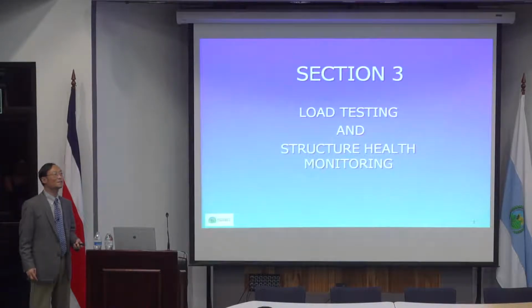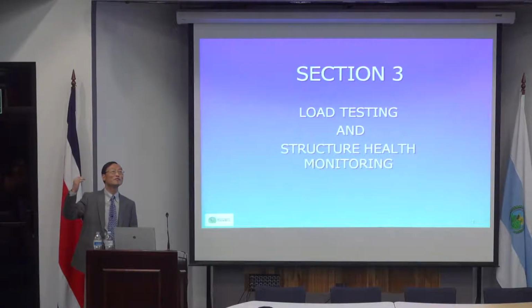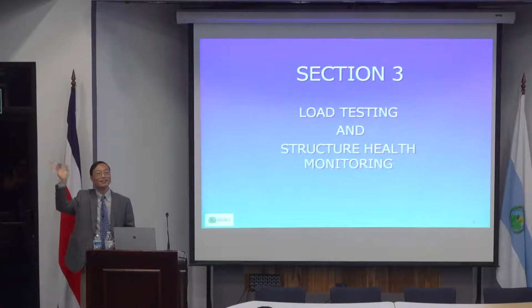And so these are two fundamental things. Once you have these things, then you can develop your finite element model based on that. Finite element models typically have longitudinal elements, which will be your girders plus your deck, and these are elements.